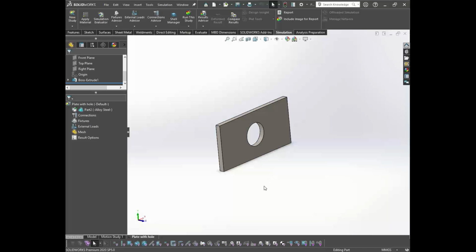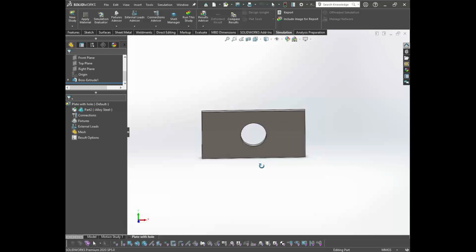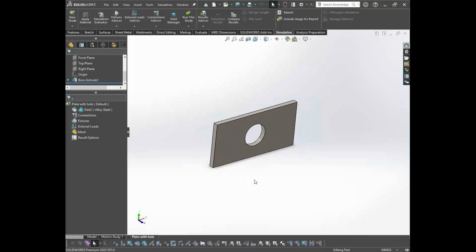Basically, we calculate elongation in any component as FL by AE. I told you in the earlier session: force times length divided by cross-sectional area times Young's modulus. So your elongation is inversely proportional to Young's modulus, right? In whatever direction you are applying the load, if you are considering orthotropic material, the elongation due to this load will depend on the Young's modulus value that you are feeding to it. Understood? Or is there confusion?